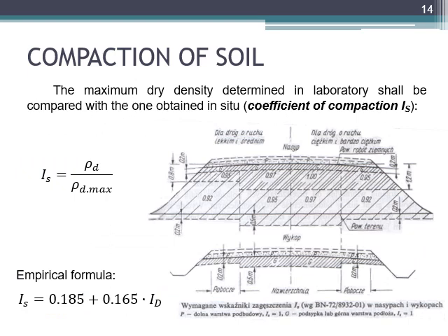The results of the Proctor test, so the optimum water content and the maximum dry density, are used in practice when road embankments are being built. First of all, the optimum water content is used to prepare the soil for each embankment layer, because we would now know how much water we shall add to the soil to obtain the best effectiveness of compaction.